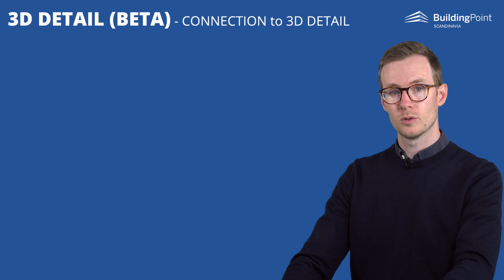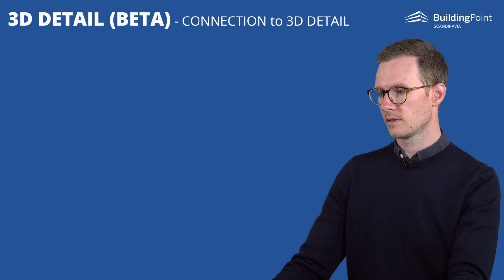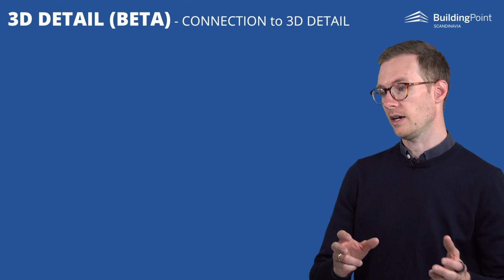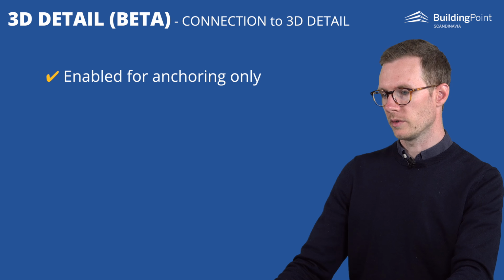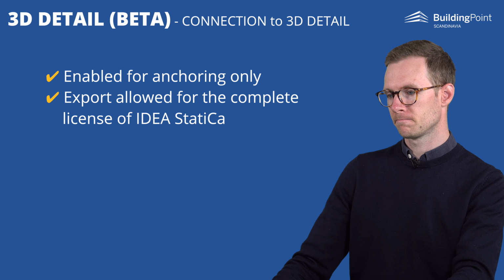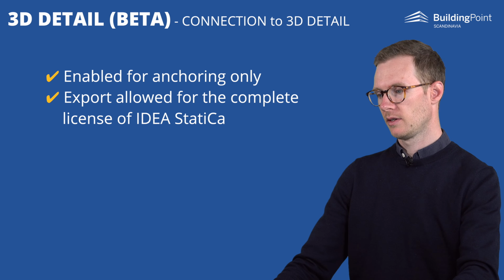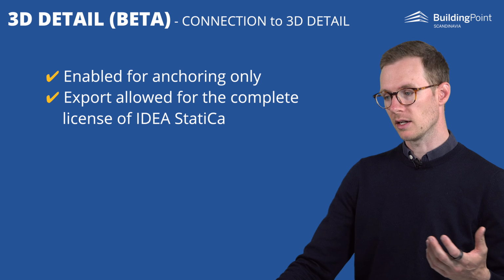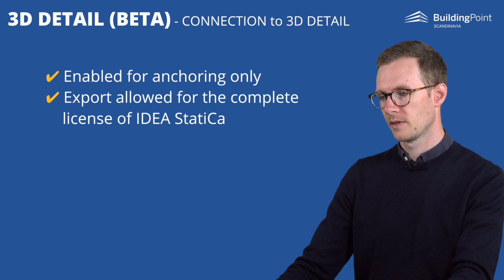And another cool feature that is new with this release is the connection between the connection application and the 3D detail. So it's enabled for anchoring only. You can then export if you have both the concrete and the steel license available, because first you have to model the connection in the steel part and then transfer it over to the concrete part of IDEA StatiCa.